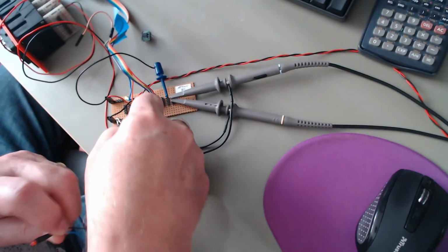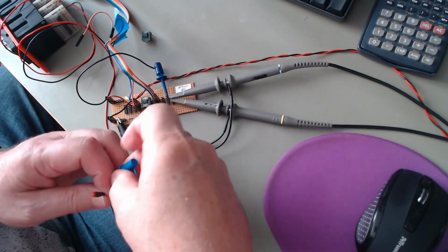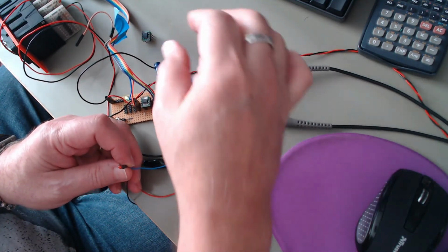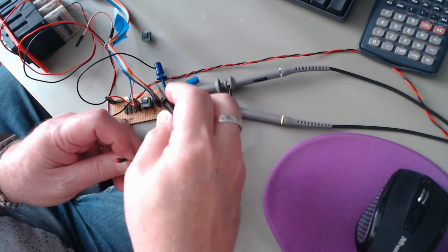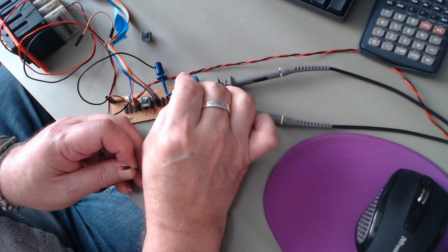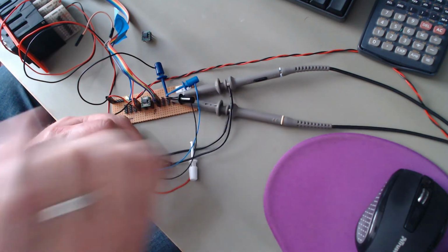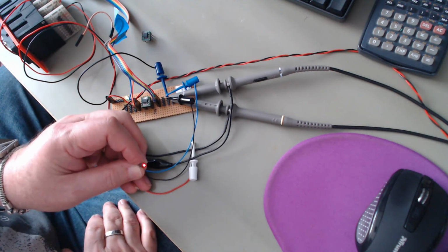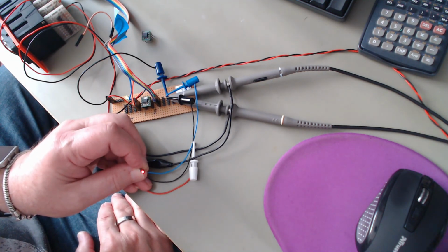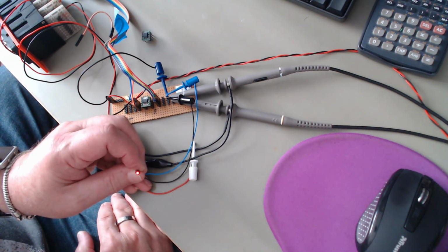But if I connect VCC via the diode and resistor to pin 7, we can see the diode lights up because it is in fact being pulled low. So that does show you that there is an active low but no active high.